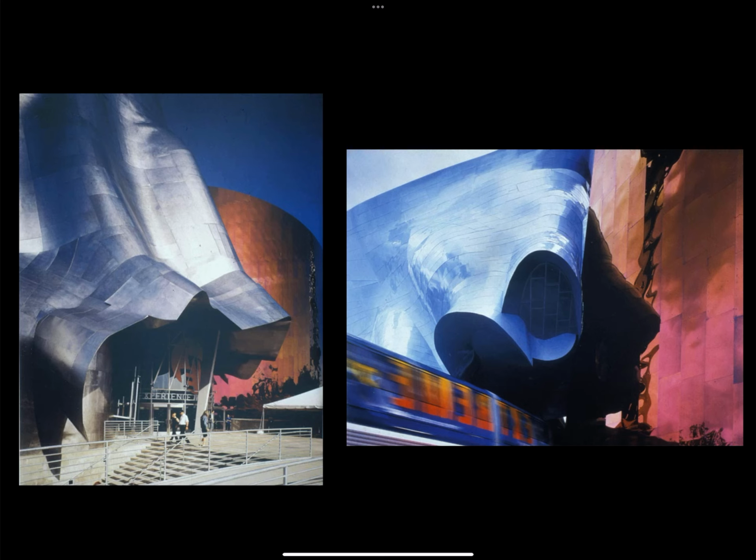In terms of impact damage, steel is very tough. It's highly resistant to impact damage. It doesn't dent easily. And aluminum, as we know, is prone to dent very readily. So it dents easily. It can easily be damaged both during construction and during the life of the building. In terms of cost, steel is less expensive, aluminum is more expensive.